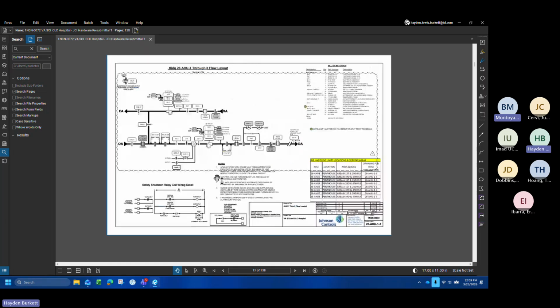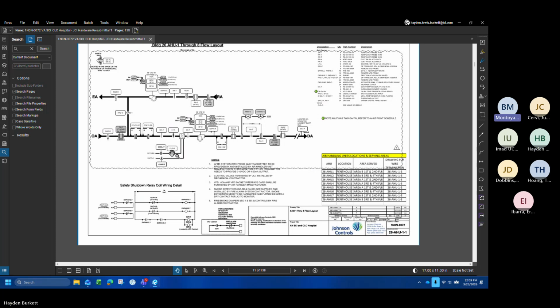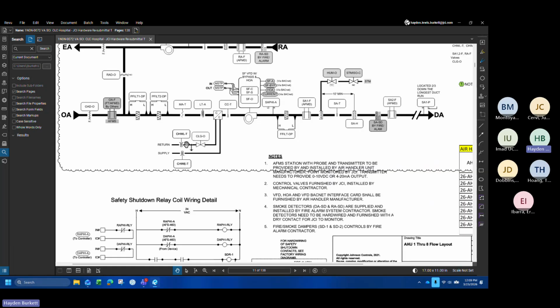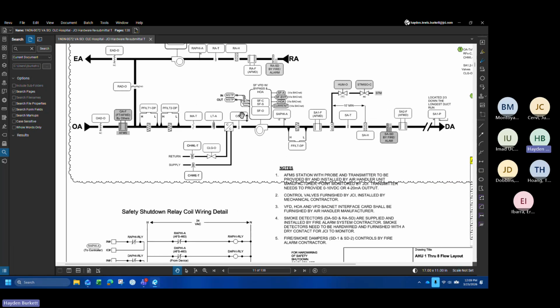Okay. Is there any part of the control system that monitors that temperature and alerts us that, hey, I'm not getting the water temperature I need? Yeah, really excellent questions. We are monitoring the chilled water leaving and entering temperatures of the system, and this is per air handler. So we could tell you what each air handler is kind of receiving from the plant. We also have a cooling coil temperature, which is actually the air immediately downstream of the coil.